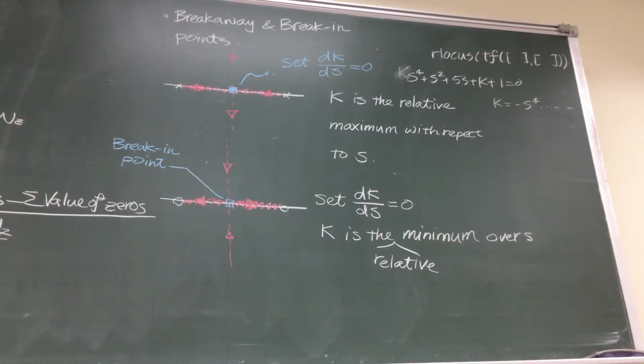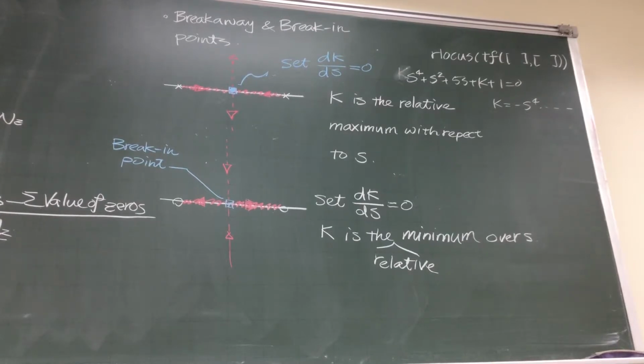First, we determine our poles. That is something we draw on the S domain. Secondly, I have two poles and no zeros, so the number over here is going to be 2, which means I can determine my theta A. That is going to be plus minus 180 degrees divided by 2, so it's going to be plus minus 90 degrees. Which is not news because we have done this example many times already.